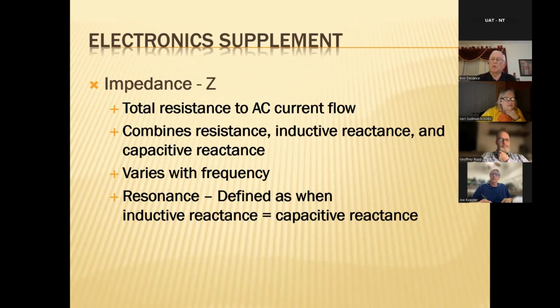And then we have another term to throw in there called resonance. Resonance is that spot at which the inductive reactance is equal to the capacitive reactance. And when that's the case, they cancel each other out.